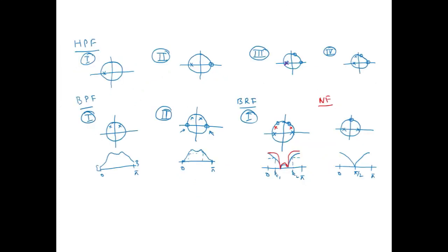Now with that analogy, if you look into the high pass filter, you can have a high pass filter like this. If you see at the low component, there will be some residual value, which can be eliminated by placing a zero at 0.